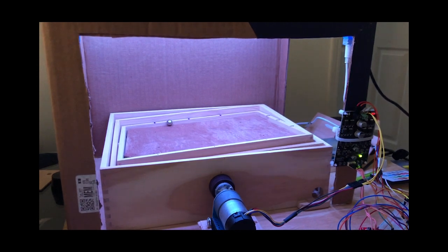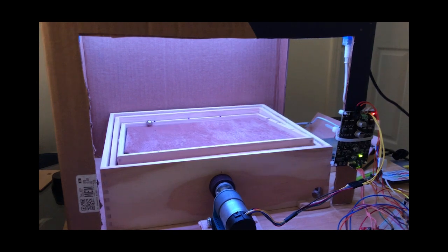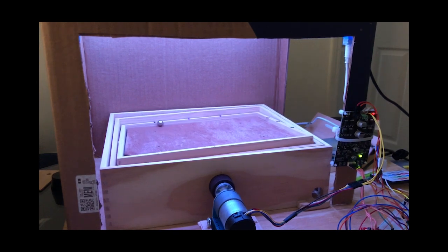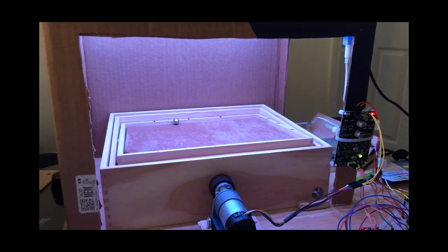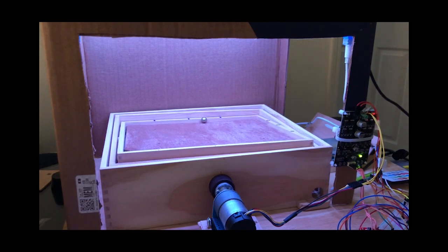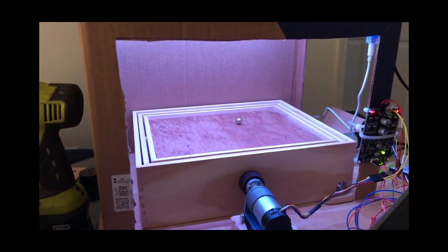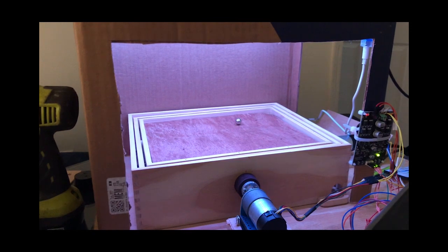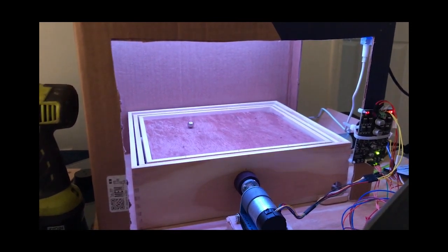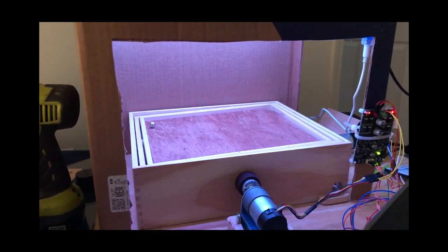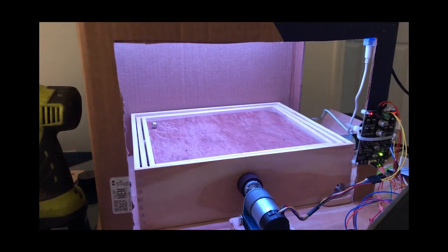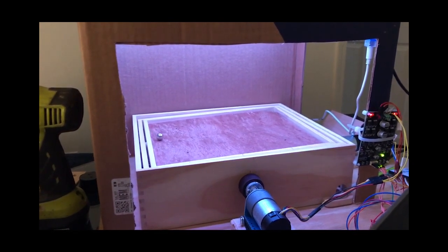The camera is constantly tracking the ball, and as the actual position of the ball gets closer to the desired position, the board tilts less and less until the ball settles in the correct position. These two pieces of information put into the ball controller create an angle for the board to tilt in each direction, and this angle is then sent to the motor controller to determine how far the motors need to turn to reach the correct board angle.